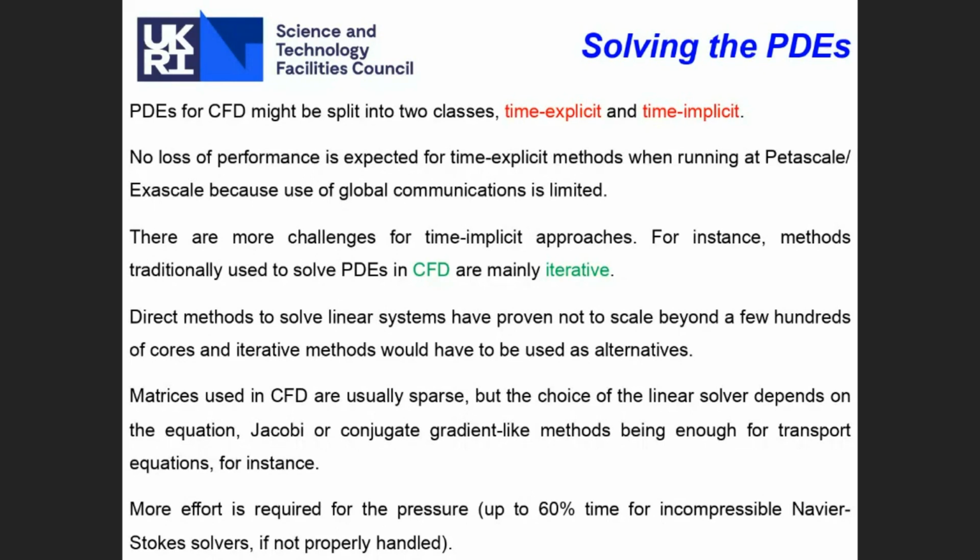So you've got a block matrix with UVW. Another part which is quite costly in solving the equations is what is called gradient reconstruction, when you've got cells which are very skewed in the mesh.